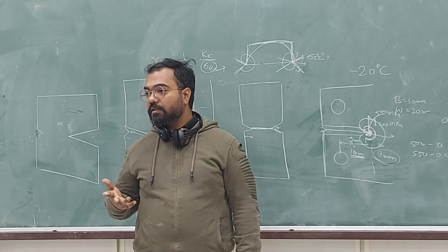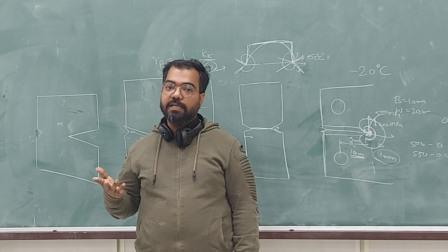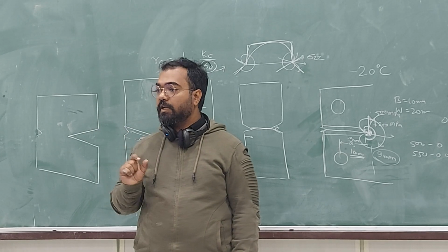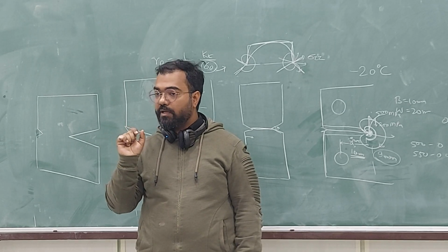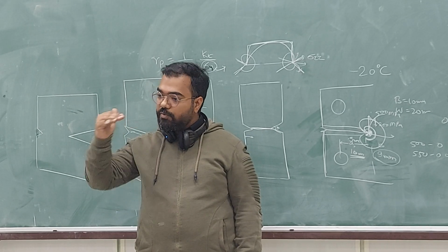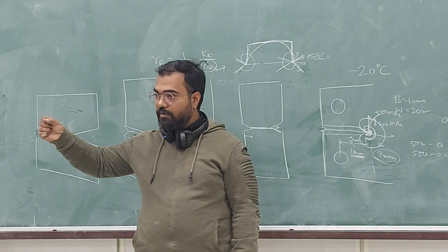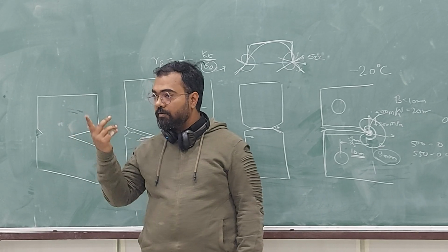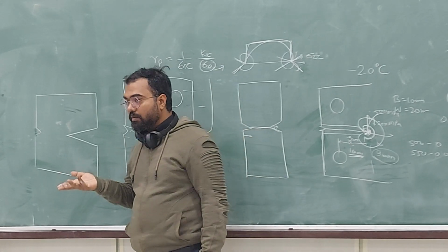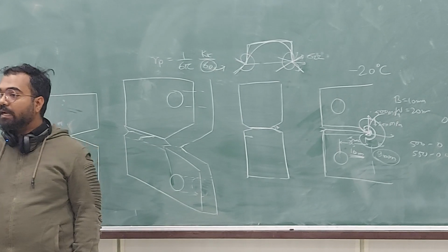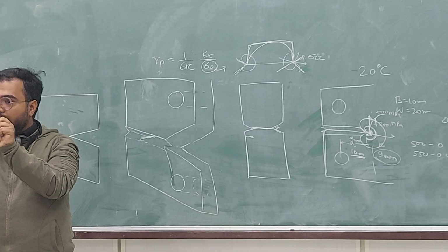So you usually use either your eyes with a polished surface on metallic materials, or you put a low magnification optical microscope. And the side groove, because you have cut it, will be shining and you have a line. You are supposed to have a line, but it will not be a line because you will be making it with wire EDM or some other cutting tool. So it will be reflecting too much and you will not be able to see if the crack is really along that plane or not.